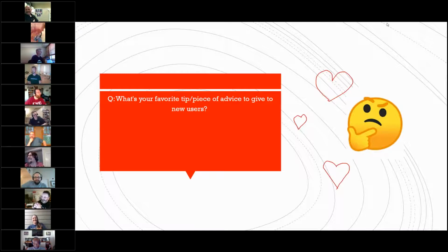I like this one as far as a tip goes. If you have transparent parts in your assembly and you're trying to click the surface of it, you can't. We all know what the tip is there, right? Hold the Shift key, and now you can click the surface of that transparent part. Yeah, all day long. Or the opposite, if you over-check the option to let...